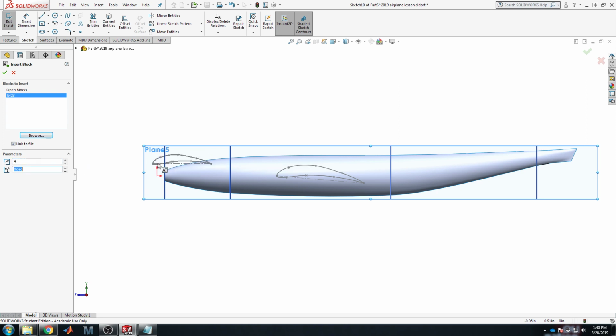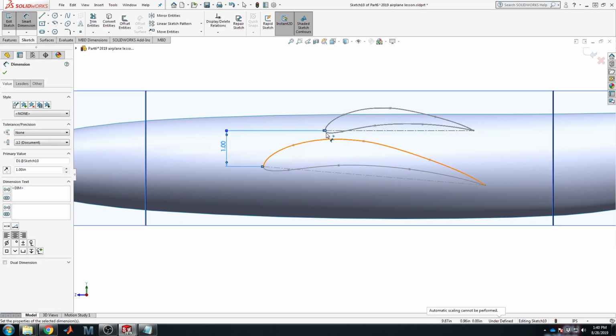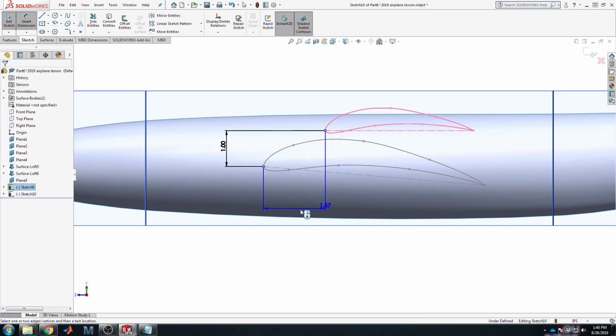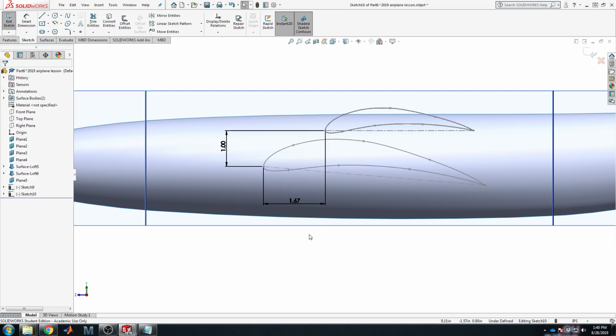So 4-inch chord, and that already gives it a decent amount of washout. And this is where you'd set dihedral, how far up and back, dihedral line sweep really, you want the wingtip to be from the root. So actually I'm going to set this up, and this is the dimension I'm going to be modifying a bunch, so that the quarter chord is unswept, which will be a little bit challenging, but for right now we'll just keep that dimension at whatever it was.